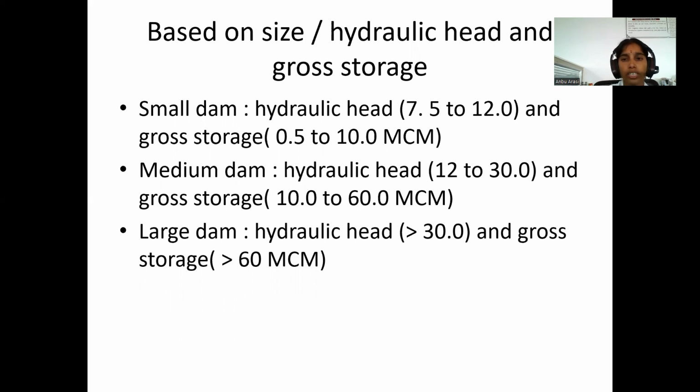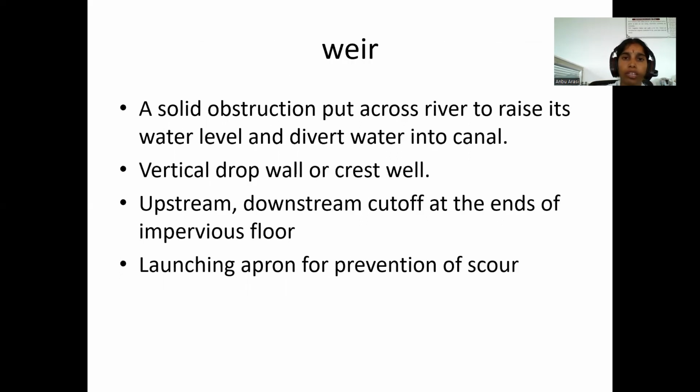Small dam: the hydraulic head is 7.5 to 12 meters and gross storage 0.5 to 10 mcm. Medium dam: hydraulic head 12 to 30 meters and gross storage 10 to 60 mcm. Large dam: hydraulic head greater than 30 meters and gross storage greater than 60 mcm.